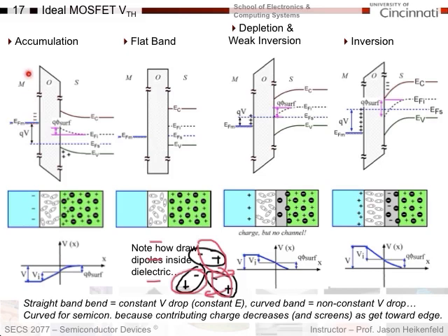That raises the bands up, right? Negative charge associated with that. Positive charge showing up here as holes are accumulated. I've got electric field, so the bands have to bend for the oxide and for the semiconductor. Okay. Here's my voltage drop, negative voltage on this side, voltage drop across the oxide. We expect that because I can see this electric field, and then voltage drop across the semiconductor. This side's grounded. Okay. Now looking again inside here, you can see for these dipoles here that they reorient a